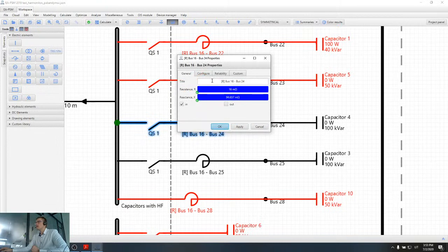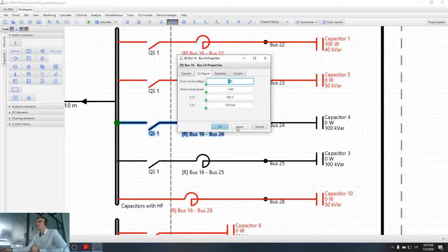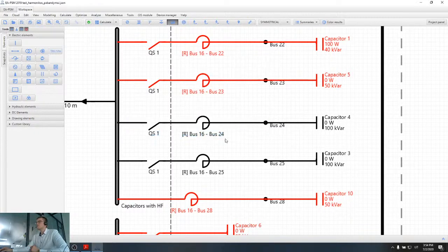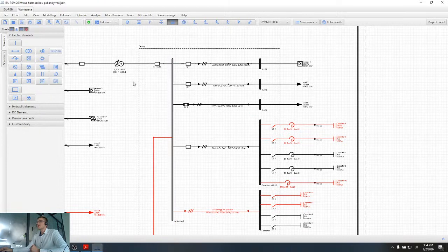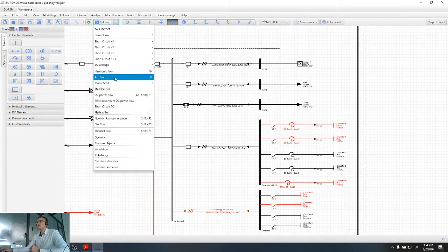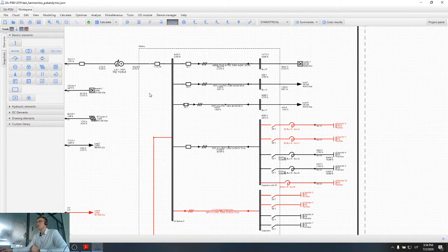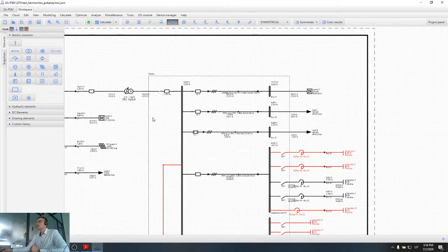So now the reactor here is selected to be 6%. Normally you have several steps of the capacitor reactors, which are provided by the distributors of the equipment. So now I selected one of the smallest possible sizes. There you can buy also like 3%, 7%, 11%, but now I selected 6% impedance. And I will calculate harmonics again, harmonic calculations, with these capacitors connected.